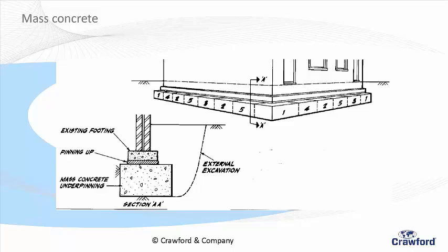And this is how you dig down. It's 1 metre section. Because if you take 1 metre out, on brickwork, the brickwork self-supports, you don't even need to say. Any wider, and suddenly you've got things falling into the hole. So you dig down, and you hand dig, or you might use a mini digger.